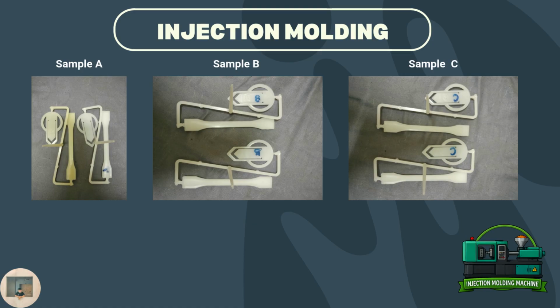This happened because polypropylene is a shear thinning polymer. When we increase the screw speed to 25 rpm, it creates a high shear rate that untangles the polymer chains, making them slide easily. At the same time, raising the temperature to 200 Celsius weakens the force between molecules. Together, these factors drop the melt viscosity, allowing the plastic to flow smoothly and produce a perfect defect-free part.